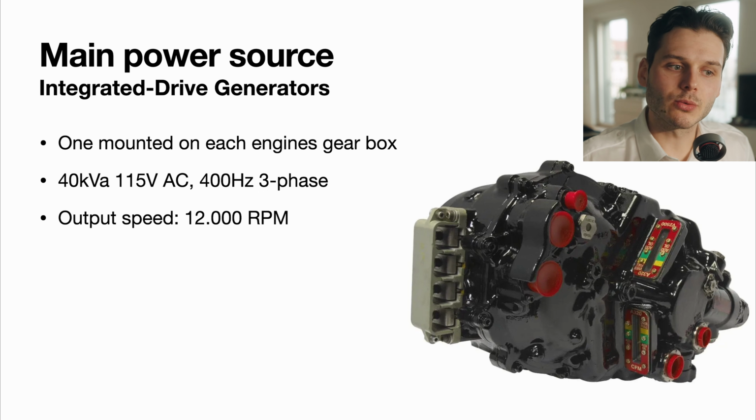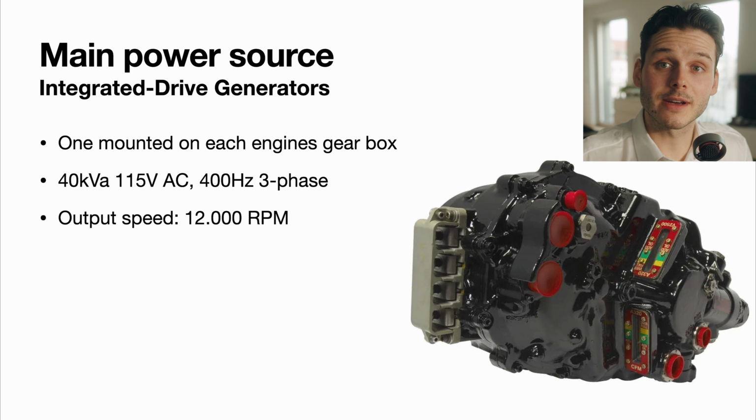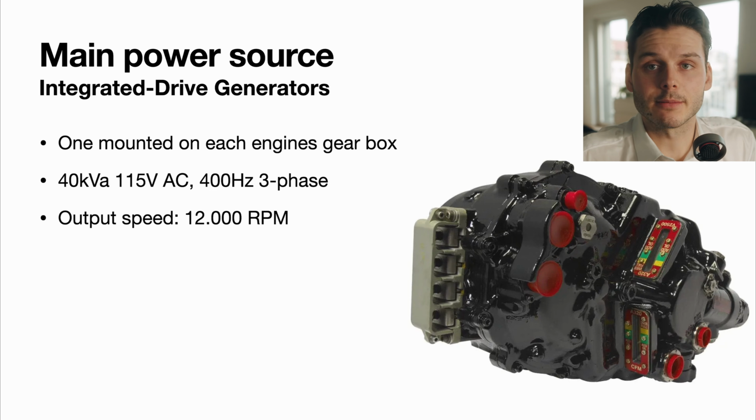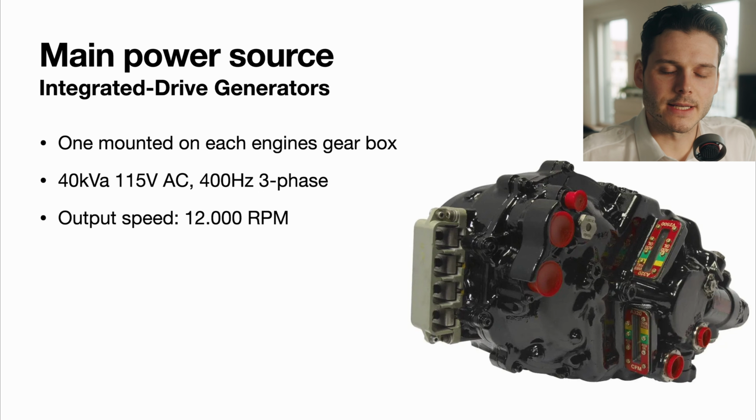Obviously, during an engine failure, we also have only one IDG working, and this is actually the reason why we switch on the APU so fast during an engine failure, which Sully Sullenberger also did during his dual engine failure. He switched on the APU right away, which did prevent a lot of systems from going black. So that's actually something that was pretty good. And we do that as well on our non-normal engine failure checklist. We do have the step in which we switch on the APU, which does help to have a second AC source, to just be redundant on that.